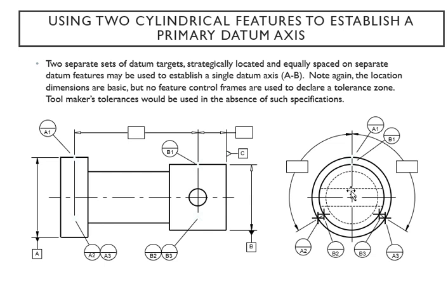So again, your front view, your side view, yeah. Pay attention to the order, and we can establish, yeah, this is your axis, and here is your datum C and B right there, okay. So now you have A and B at the same importance, yeah, because they're tied anyway. So that's what we call the single datum axis, because you are dealing with two circles sharing the same center, yeah, see that. So therefore they have equal importance.